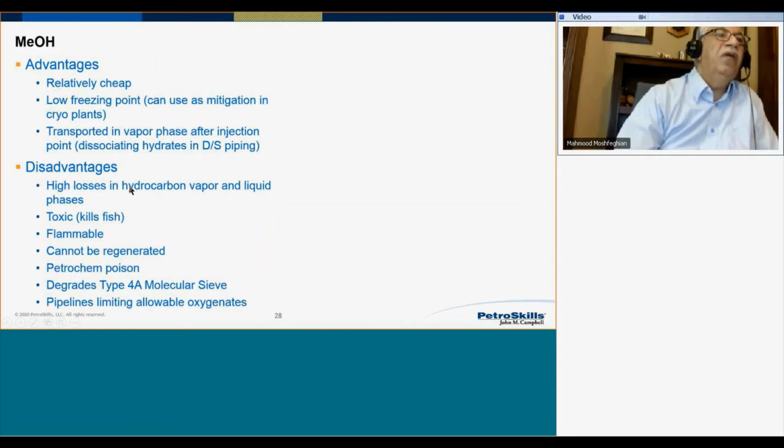Disadvantage: high loss in hydrocarbon vapor and liquid, as you saw in that case study result that I showed. The rule of thumb is that generally the loss of methanol to the vapor phase is 2 times the rate needed for the methanol to go to the liquid water phase. So a huge amount of loss to the vapor phase. It's toxic, which damages the fishery industry or kills the fish. It's flammable, cannot be regenerated. Well, we can regenerate it, but it's very expensive, so rarely regenerated.